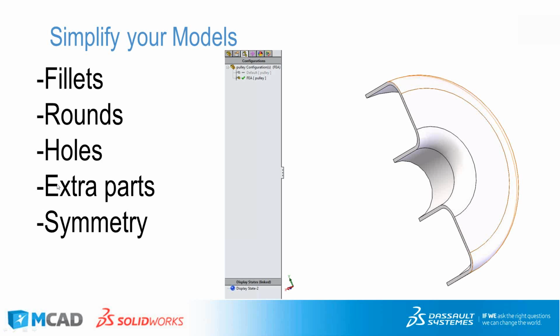That's another thing to get rid of. Extra parts, what I mean by that is if you have a multi-part assembly, but you're really only trying to get the stress state down in one of the parts of the body, don't put the extra parts of the assembly in there. Instead, cut them out and use a fixture that is a representation of the rest of the body there. So an immovable, no translation, a fixture, something to give you how it would relate to the body above it. And you can sim the same loads and such, but don't need all of the extra contacts and no penetrations and all those other things that would normally need to be solved for.